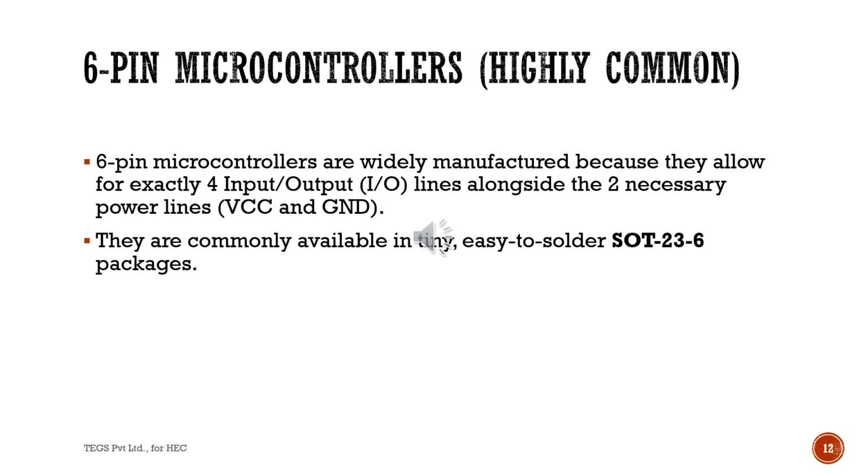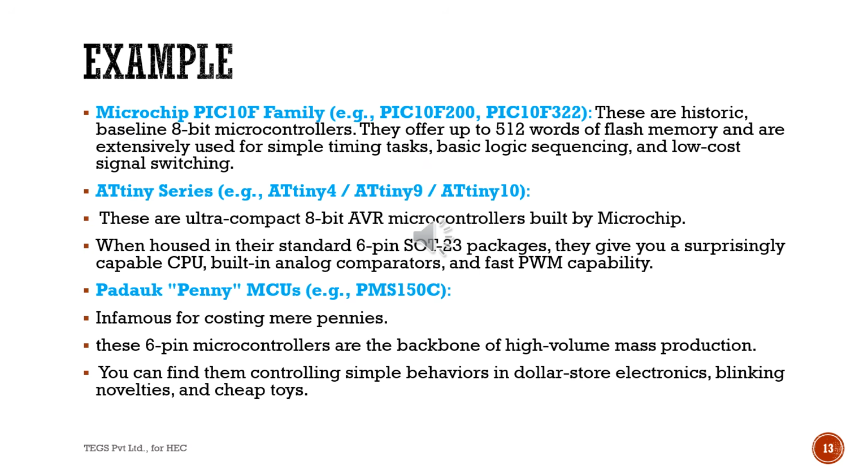They are widely manufactured because they allow exactly 4 input-output lines alongside 2 necessary power lines. They are commonly available in tiny, easy to solder SOT23-6 packages. Examples: Microchip PIC10F family, ATtiny series, Padauk Penny MCU.